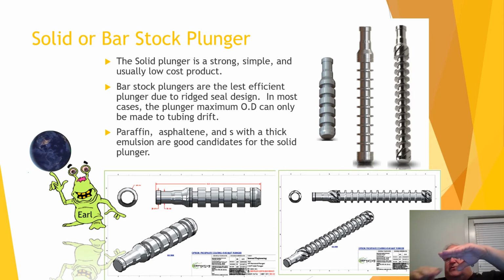Now you would think, okay, well, we've worn some material off, it should get lighter and roll over. But that's not what happens. What happens is it flops around and rolls and gets into that saddle, and once it's in that saddle, it just keeps wearing. It gets worse and worse. So if you're seeing plungers that are wearing on one side, that's really what's happened. It started to create that saddle, and then it just keeps falling in that saddle every time it gets into a dog leg or deviation.